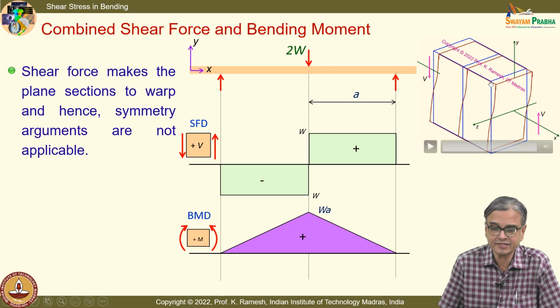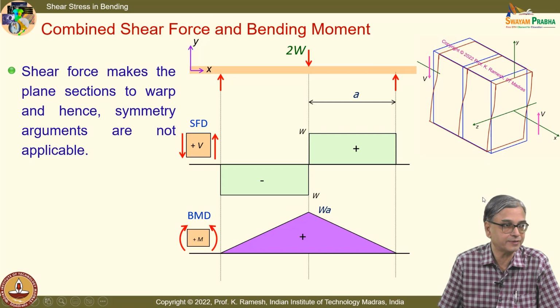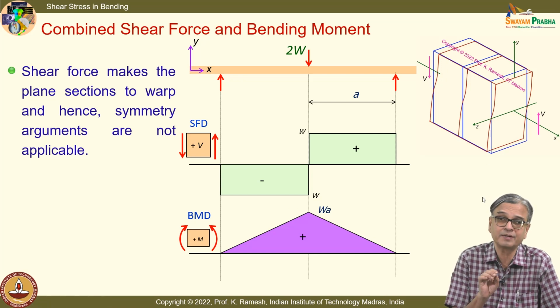We have made certain observations, like the plane section gets distorted like this, and here the original 90 degrees is preserved, which indicates shear strain is 0, which we have also seen when I have this as a free surface. Even though I may have a shear force transmitted by the beam, the distribution which you evaluate from strength of materials should be such that it has to be 0 at the top point as well as at the bottom point. That we have understood from the discussion on free surfaces.